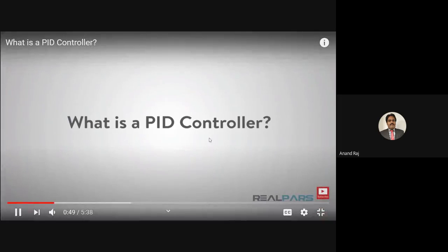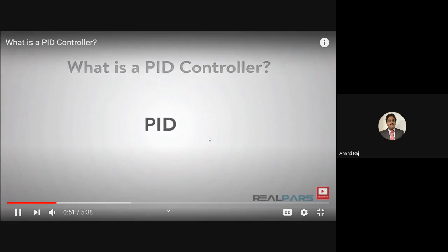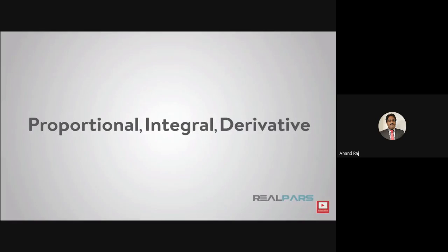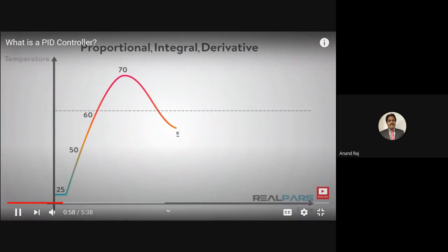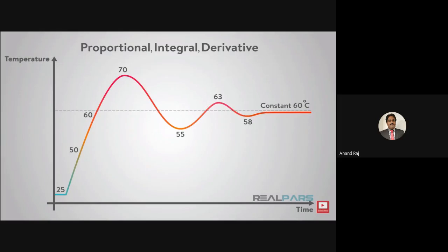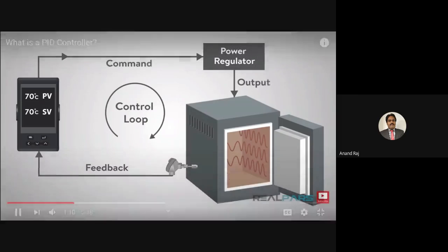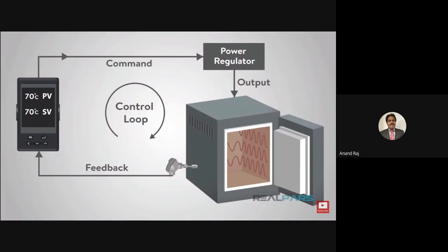So what is a PID controller? It is an acronym that stands for Proportional Integral Derivative. If you need to keep something constant, like a temperature for example, then this is the way to do it. Essentially, it uses a control loop feedback to ensure the output wanted is what you will get. Simply, you put a setting in the controller and it will keep the output constant based on feedback from some input, typically some kind of sensor.